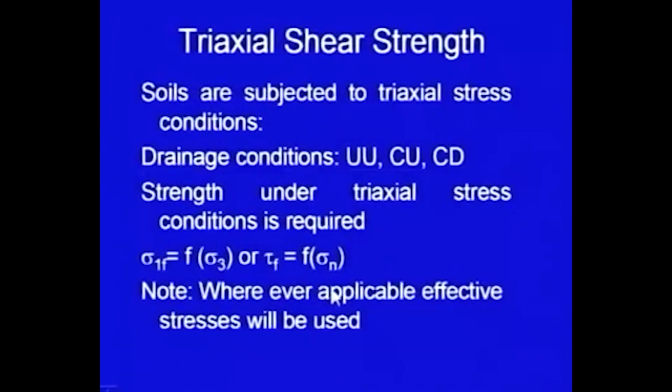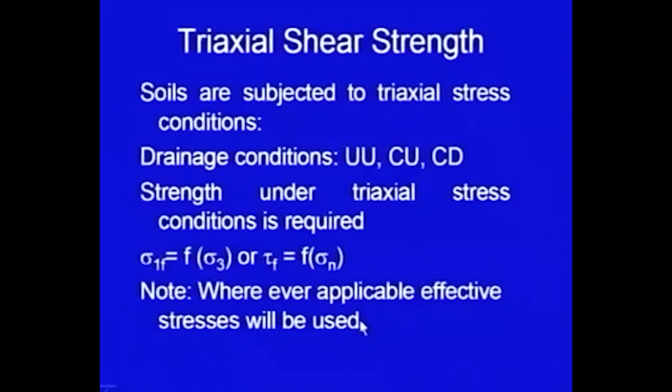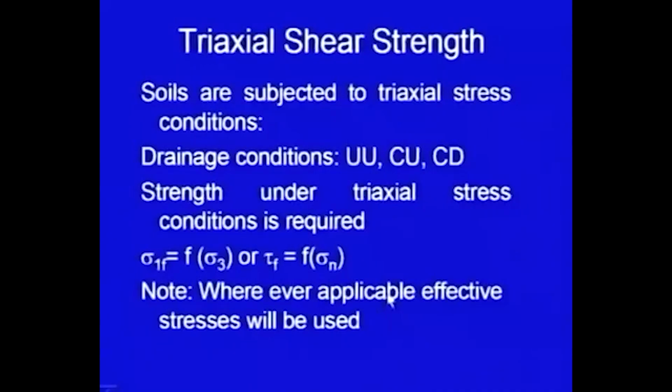We have discussed the consolidation test. Now, the second most important thing which I would like to go through briefly is the triaxial shear strength, or simply the shear strength of soils. Whenever you talk of the bearing capacity of soils, or slope stability analysis, any kind of analysis in soil engineering, we always talk in terms of the shear strength of soils. We assume that the soils are failing in shear.